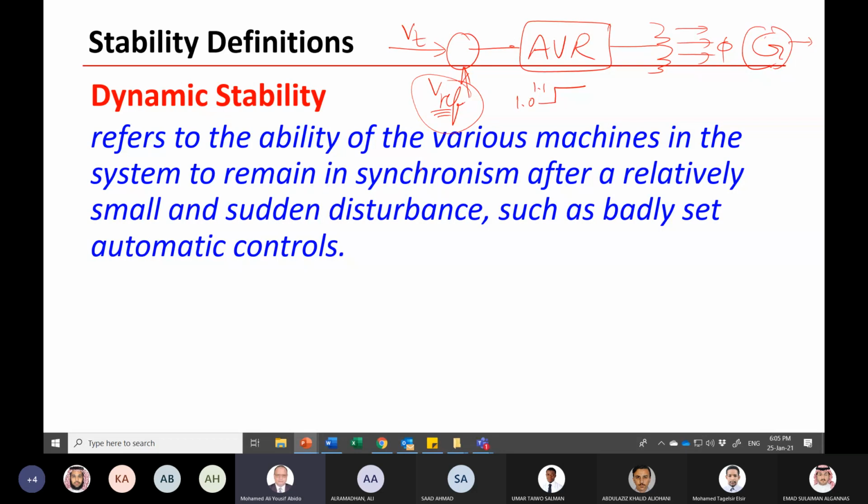Of course, you have also the transformer taps, you have shunt compensation in terms of capacitors or static var compensator or STATCOM or whatever, or synchronous condenser. You can have other types of solution, of course, but one solution to solve the low voltage at certain buses is to increase the VG, the generator voltage. The voltage here is 1 per unit. Okay, that's fine, 13.8 kilovolt.